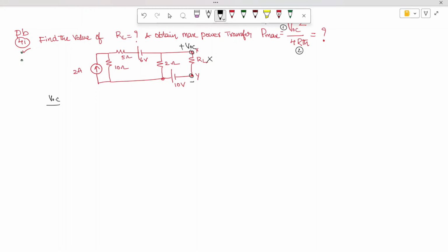But before solving, you can see here this is like a practical current source. I am going to apply source transformation. Okay, so when I apply source transformation, let us assume I'm connected between node 1 and 0, and this is node 2 and 0, all are zeros. Okay, so now between 1 and 0 I'm going to reduce it, and I'm going to use source transformation. The value of this resistor is 10.